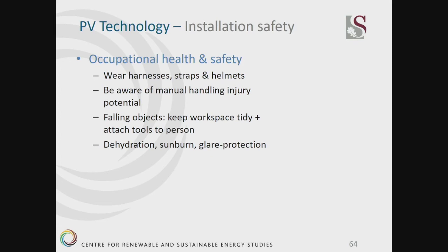Take care of falling objects, and this is more for the installers, so they must keep the workspace tidy and attach tools to a person. If a plier falls off the roof and it hits somebody on the head on the ground, that might be a serious injury. Take care of dehydration. Installers are working in the sun, so take care of your people. If you are an installer, make sure they are hydrated, protected against sunburn, and also have glare protection.